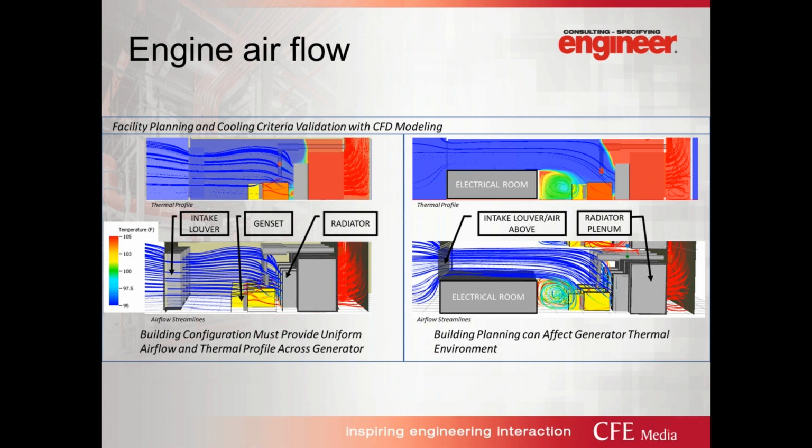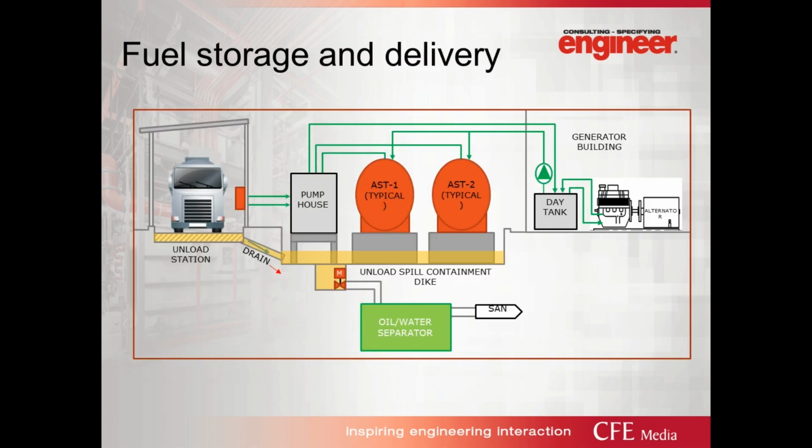Fuel storage and delivery. Hospitals are in the same boat here, but how many hours of runtime on diesel fuel do you want? What does your bulk storage look like? What does your local storage close to your generator look like? Oftentimes, you have a lot of generators in the same room. There are code limits for gallons of fuel within the room for day tanks, and you need to understand as these generators get larger and larger, up to 4 megawatts each right now, these day tanks can get very sizable, and it becomes a real concern that people need to worry about.